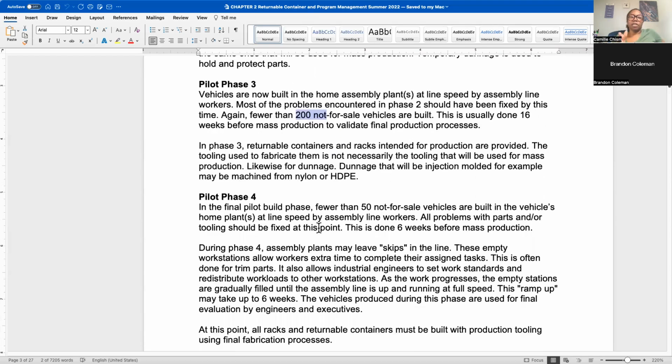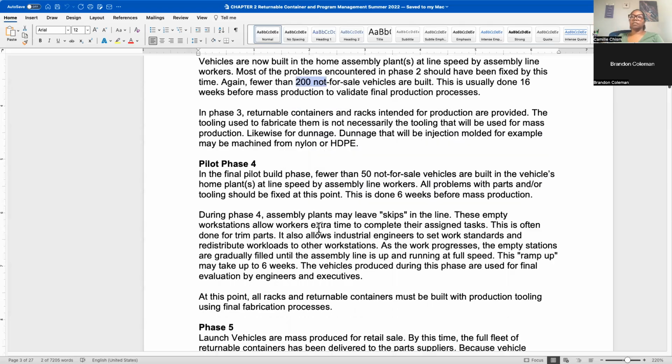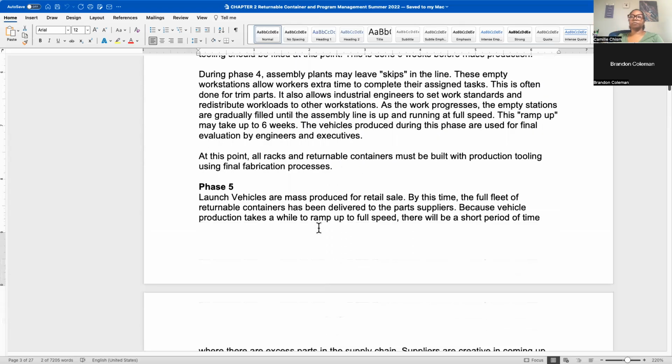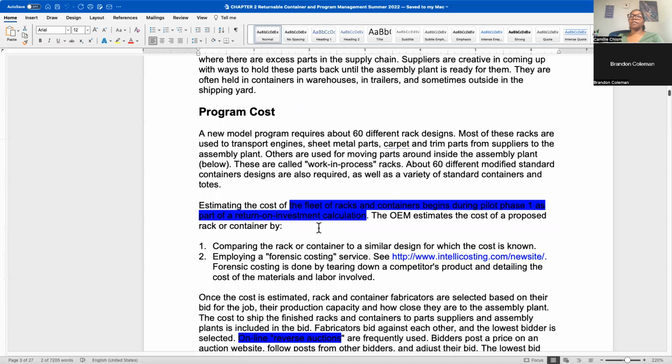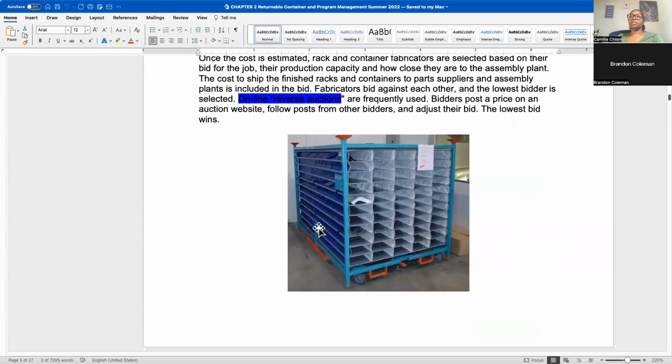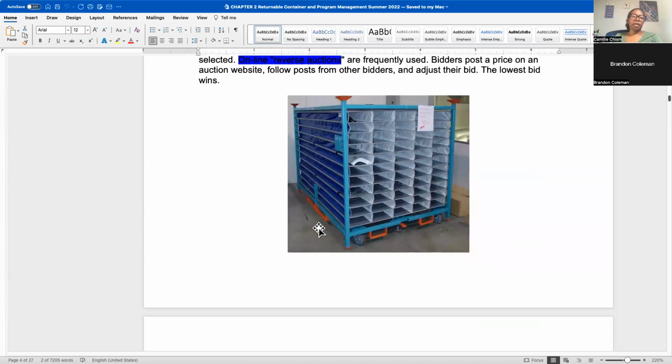So as you look at your schedule, you also want to back into anything like a rack or anything that requires tooling that may take months to get. How does that look? When do I actually need to start ordering that to meet production starting in phase 4? A lot of times you'll get Gantt charts. A Gantt chart basically looks like a spreadsheet, and it has a calendar on it.